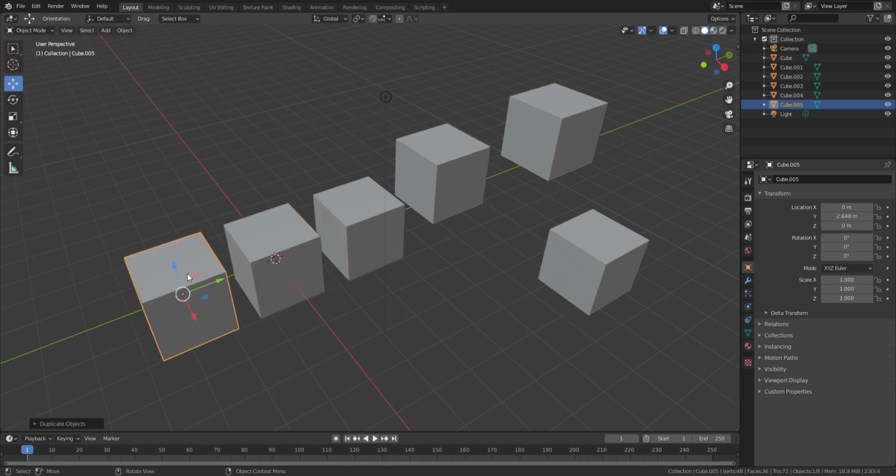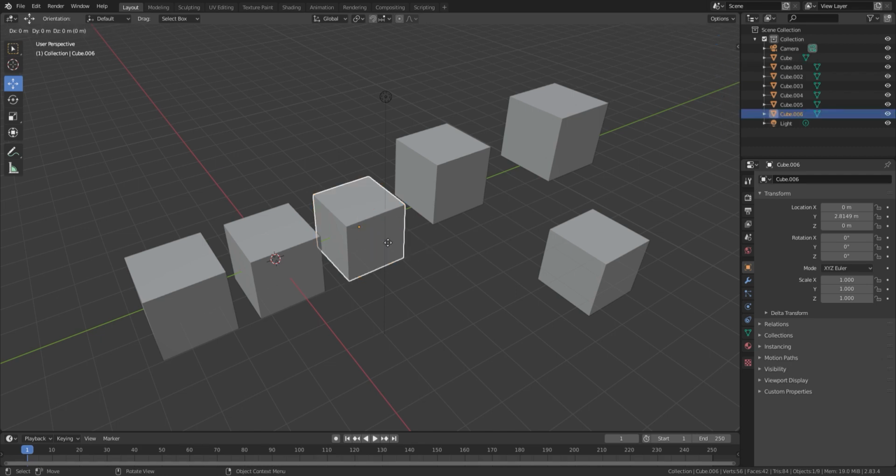In case you're an absolute beginner and you're unfamiliar with the directions, the compass in the upper right corner would help you out. So if you wish to move upward, you just need to press Z after the Shift-D command. It's okay if you move the cube in another direction before that, because by pressing the Z button it jumps straight to the right position. After that you can only move it up and down.